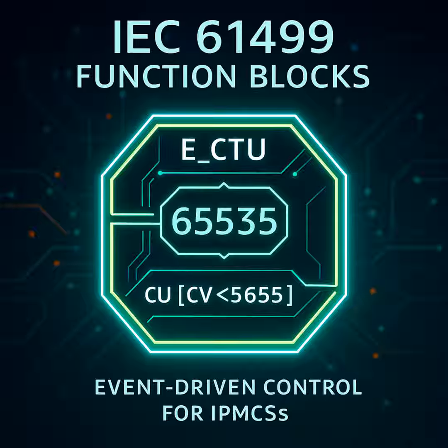Okay, events tell it when to act. Now, what about the actual data, the numbers? Right, the data interface. It needs one key data input, PV, which stands for preset value. That's your target count, the value you're counting towards. Exactly. And then there are data outputs. The main one is CV, current value. That's the actual count it's holding. Okay, PV is the target, CV is the current count. What kind of numbers are these?